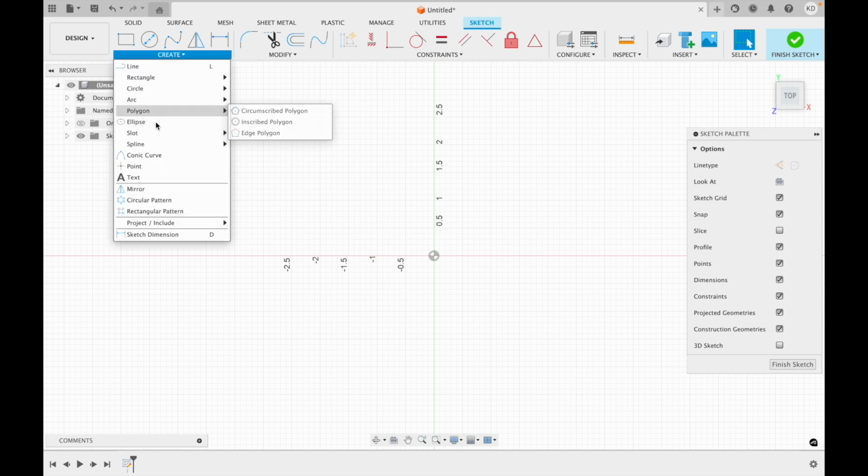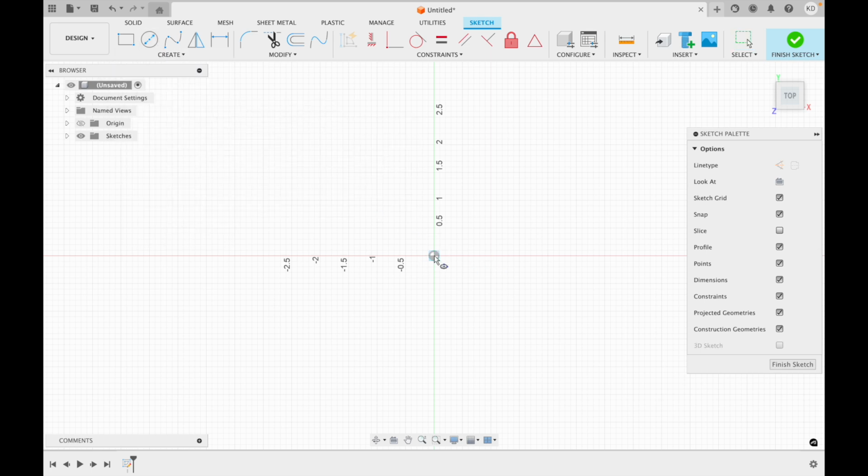And I'm going to show you a couple of things. But the sketching is pretty much the same, except it's with an ellipse, where I dimension it out because I needed the dimensions specifically. I do recommend that you type out your dimensions if you are looking for specific dimensions. If you're just practicing modeling, designing, it doesn't matter too much, but if you want to build and 3D print something, do type out your dimensions.